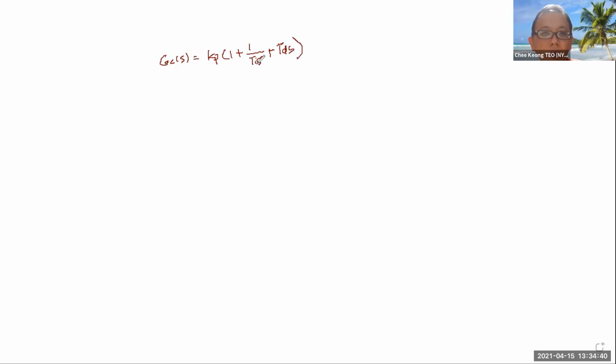Now again, you notice that this is I, so it's the I controller, and this is D, so it's the D controller. So this is basically a PID controller. This is P, so it's a P controller. So the subscripts are also specifically chosen. If you multiply this out, it is Kp plus Kp over Ti S plus Kp Td S. Now this is the Ziegler-Nichols formula.